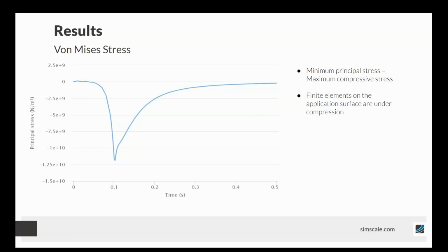They're only on the surface, these application surfaces. So I think we'd be pretty confident that this thing's not going to break apart, but we do have very high principal stresses. So for something like fatigue analysis, it may be very important to check these maximum values and see what the life of this will be for exactly the surface elements,